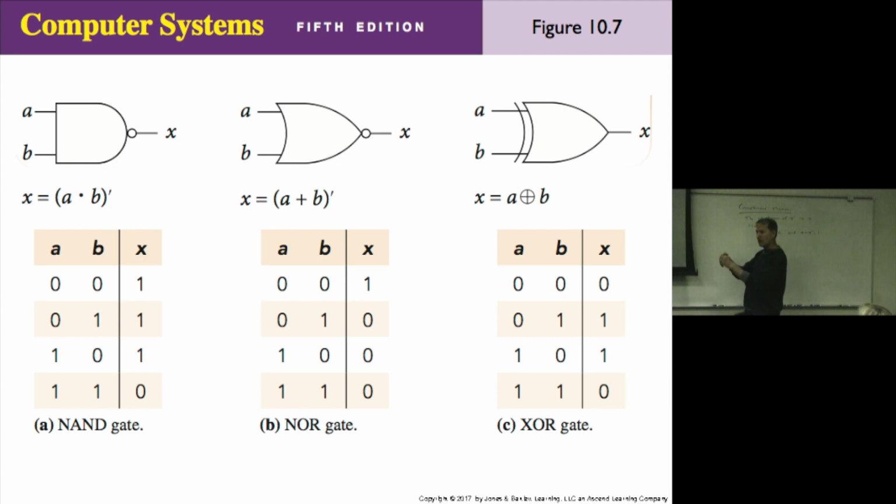You draw the OR, and then you just shift your template a little bit to the left, and then duplicate that curved line. Are you with me? So that's an XOR gate, exclusive OR gate. And the mathematical symbol for that is a circle with a plus in it. Because plus, in this system, is OR, and so you put the circle around it, that makes it exclusive OR.